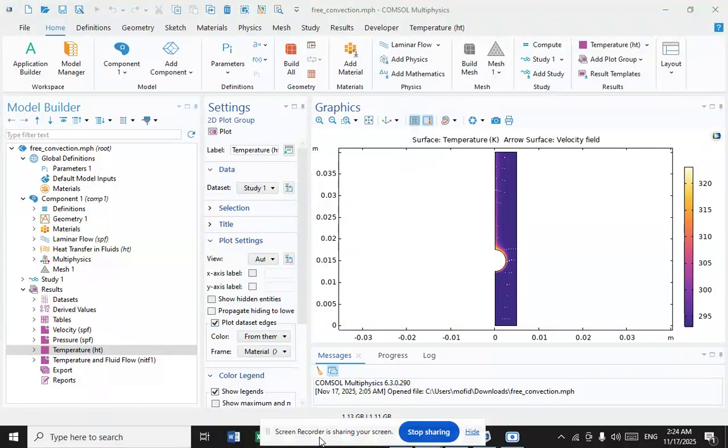This approximation correlates the coefficient of volumetric expansion of a medium β with the gravity acceleration g, and they enter into the governing equations only as a product. Physical substantiation of this approximation is based on the smallness of acceleration in free convection fluids as compared with the acceleration due to gravity. Comparison with vast experimental material indicates that this approximation well reflects the main specific features of thermal gravitational convection in a wide class of real convective fluids.